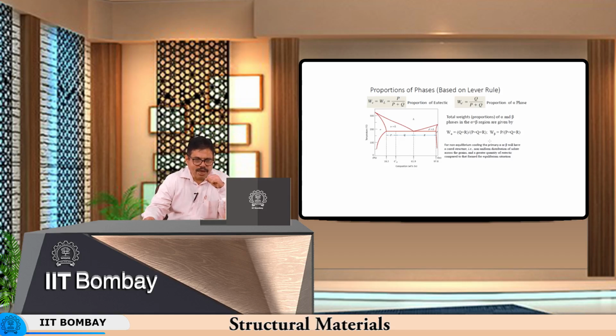So, you have this as the fulcrum in one case, basically you use this as the fulcrum because the composition is C dash 4. So, this is the fulcrum, and then you calculate the amount of eutectic and alpha dash relative to this. So, you have this side upon the total length, and this side upon the total length, determining the percentage of eutectic.